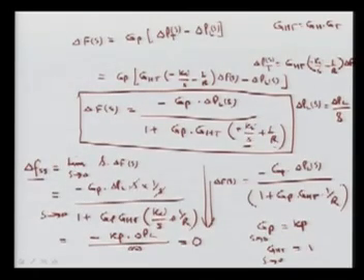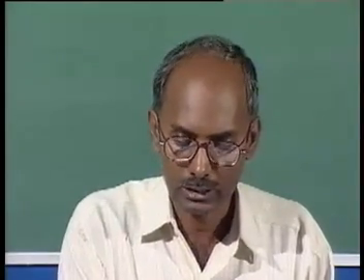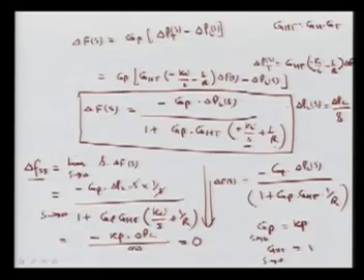Now let us see for this closed loop transfer function, means change in frequency is related with the change in the load, and we want to see the performance in the sense of the step change of this PL. What will be the performance? Again, let us take Ki as a value. We will not put the exact value. To see this, as you know, we have to again ignore the time constant of GST, we can say it is very small, so we can ignore it.